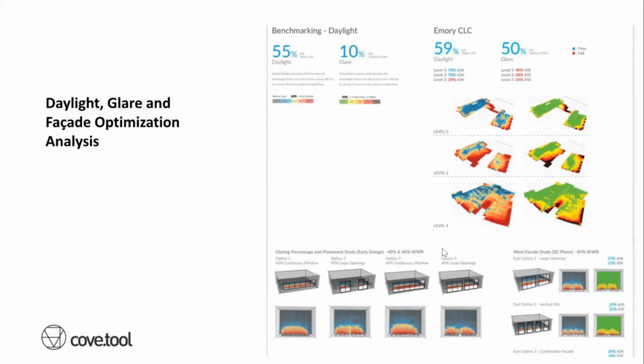But the one thing it won't do is, basically the 3D model is used mostly for the full building daylight analysis you're seeing at top. It does not have the ability to pull from the shoebox model and go back into that, if that makes sense. But you can adjust the window to wall ratio in that. So those two don't speak to each other, but I don't see why that couldn't be something they can change in the future. That's a little confusing, getting a little into the weeds, perhaps.